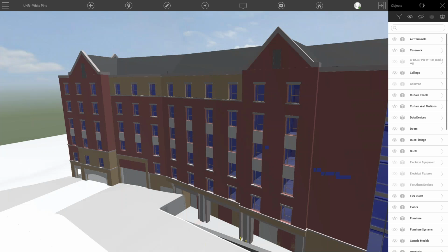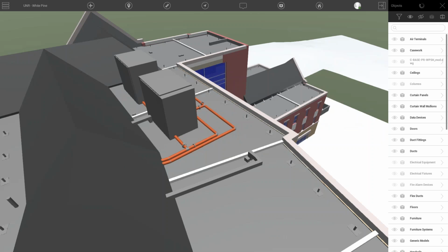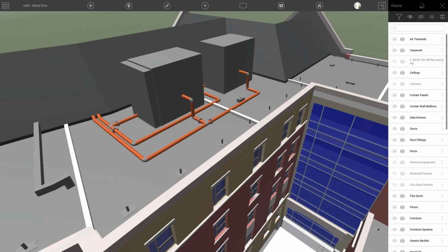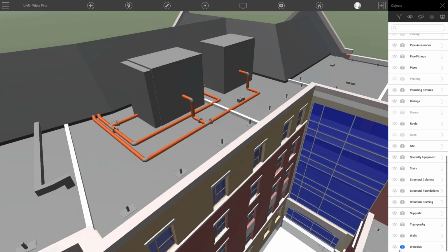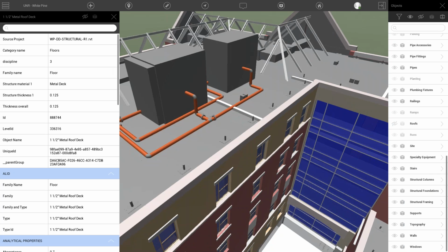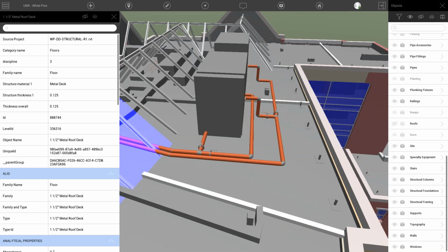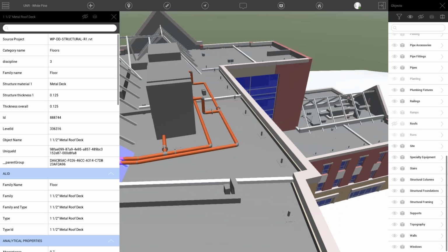Like I said, on Monday we were going through the model on this project. We went ahead and combined what we have right now, MEP, structural and architectural, so this gives us the opportunity to see where things are being routed and how they're going to route, and see if we can make some small changes to help the construction team build it easier, or change any issues they see in the future. So we're looking at these issues here, just seeing where we can route this to make less exposed piping, and some other issues.